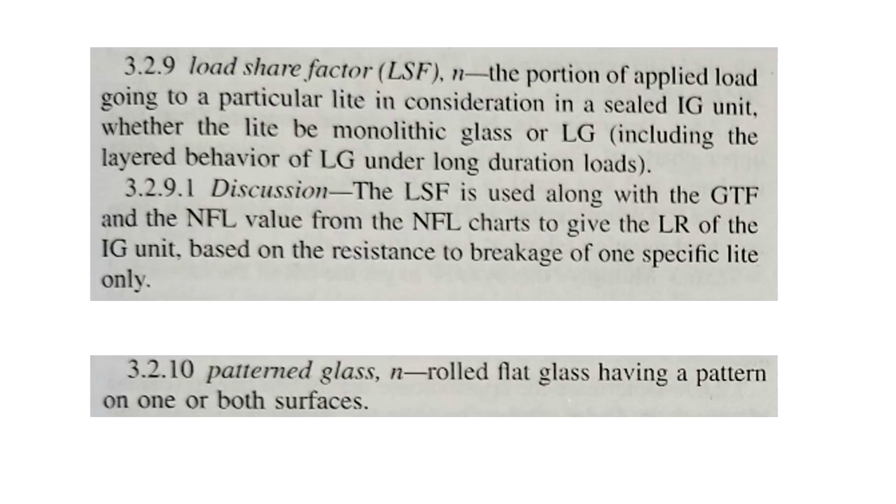Okay, load share factor: the portion of applied load going to a particular light in consideration in a sealed insulated glass unit, whether the light be monolithic or laminated glass, including the layered behavior of laminated glass under long duration loads. What in the world did they say there? The portion of the applied load going to a particular light.